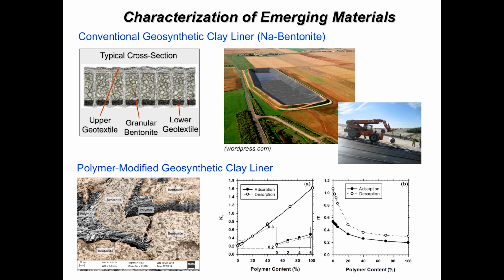One of the things that we've been working with recently is bentonites that have been modified or amended with polymers, superabsorbent polymers, to really deal with aggressive chemical environments, maybe really high salinity leachate that might be generated, really extreme pH environments that are not compatible with conventional sodium bentonite, that would collapse double layers and open up pathways to increase hydraulic conductivity.